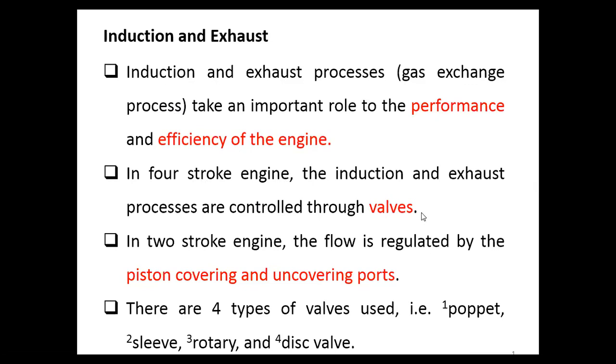Okay, for the 4-stroke engine, these two processes are controlled by what? Valves, right? We use the valve to open and close. When we open the inlet valve, the intake process happens. When we open the exhaust valve, the exhaust process or the exhaust stroke happens. Okay. For the 2-stroke engine, the flow of the intake and the exhaust gas is regulated by the piston covering and uncovering the port, right? Because we use the motion of the piston, when it moves up and down, to open and close the port.